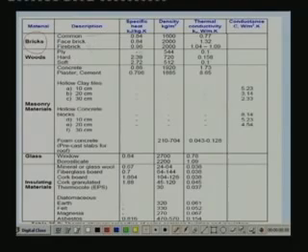For all these types of bricks, these are the specific heat values, these are the densities, and these are the thermal conductivity values. Since these are homogeneous materials, you need not give a conductance value, the thermal conductivity value is enough, and from the thickness of the brick and the thermal conductivity you can find the resistance. Next come woods: plywood, hardwood, softwood, with specific heat values and densities. Again, these are the thermal conductivity values because these are also homogeneous.